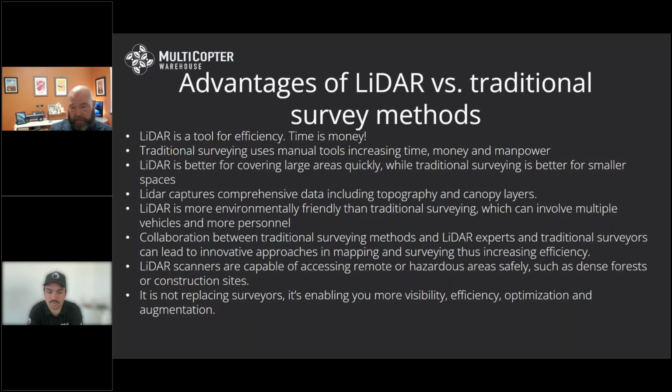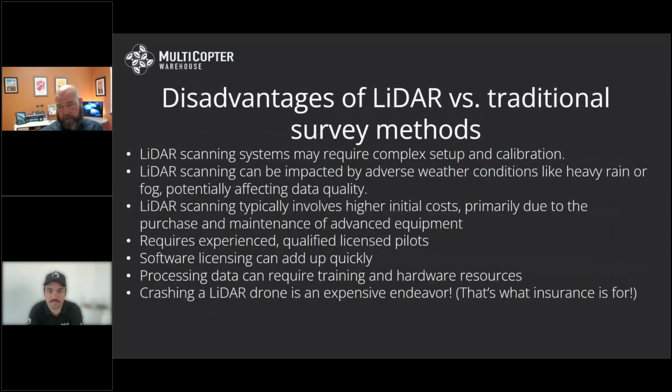Likewise, LiDAR can be used in the dark. Photogrammetry is at the mercy of the elements in some ways. We'll talk about that in a minute. But the goal here too is that LiDAR should never be replacing a surveyor. It's enabling you more visibility, efficiency, and optimization within your scope of work.